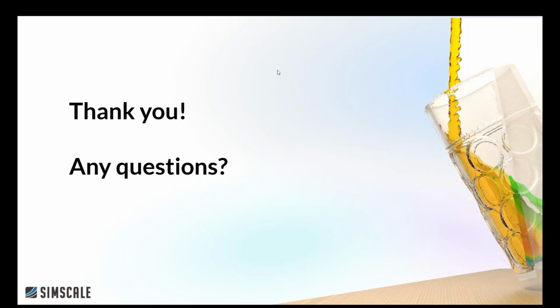What you can do is you can obviously download the results, right? So you can download all the results that you generate on SimScale anyways. So we also provide download options for Marc, and it will come in a neutral file format in VTK. So with any type of post processor, something like ParaView, for example, should be able to open the file, apply the deformation, and then export as STL. Right? But so far today, we don't have the direct option to download the deformed shape, but there's a way how it can be done.